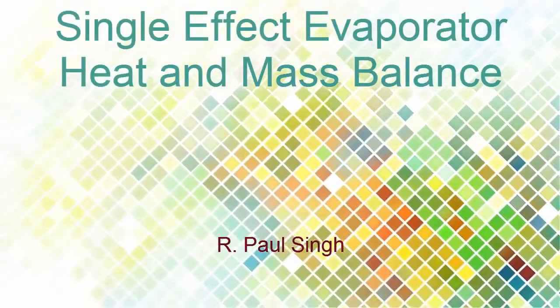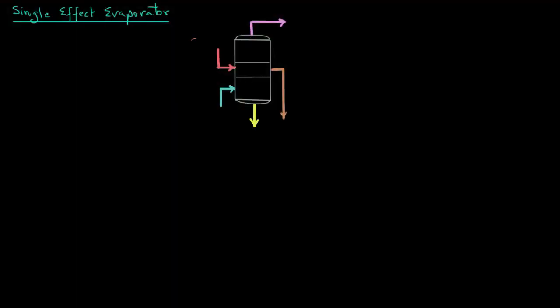In this tutorial, we will look at a heat and mass balance for a single effect evaporator. Let's look at the schematic. So we have the various streams going into the evaporator, the vapors leaving on the top. We have steam coming on the side, the feed entering at the bottom, and the condensate leaving the system along with the concentrated product. Note that the tubes and the heating chest of this evaporator is called calandria.